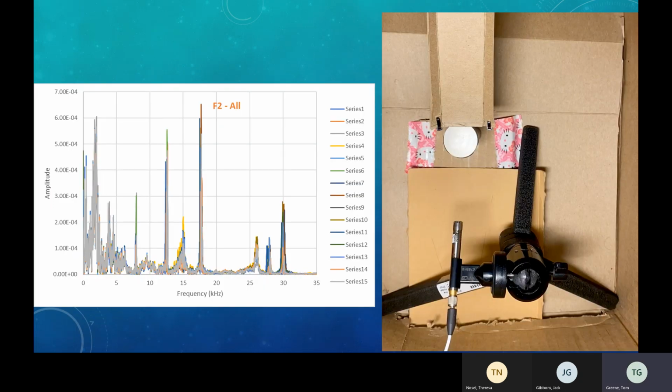The control samples in each variation were then tested in batches using our DIY fixture, and the results were used to investigate in what frequency the good parts corresponded to. This inspection occurred from around 0 to 94 kilohertz. Pictured to the right are just the results from one sample, control sample F2. In the video below, you see one run.